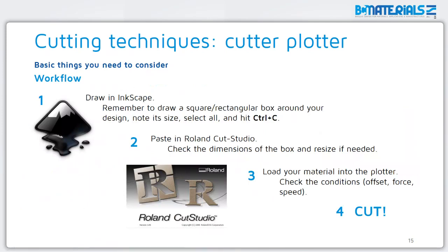Ideally the cutter plotter has plugins to work with Adobe Illustrator and CorelDRAW, but we don't have those programs available, so we can use Inkscape. The problem is that when you try to transfer from Inkscape to the plotter software, it doesn't like it very much.